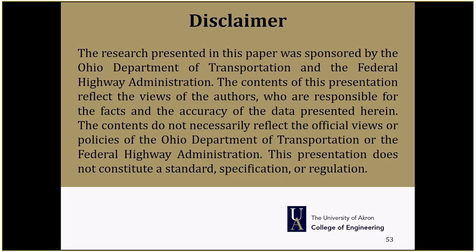For the 5 membranes we tested, is there any difference in performance of type 2 and type 3 membranes? Type 2 is peel and stick, and type 3 is the regular membrane. So no, for the 5 membranes we tested, we did not see any difference.